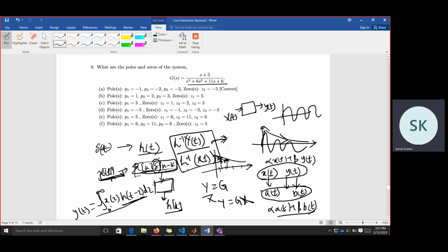Now what is the Laplace transform of the unit impulse? This is the input x, this is the unit impulse. The Laplace transform of this is 1. So Y is simply G, the transfer function. So this one is the Laplace transform of the response of the system to the unit impulse. A unit impulse is basically a shock, or you can say a sudden perturbation. So now we are characterizing the response of the system to the unit impulse in the frequency domain.